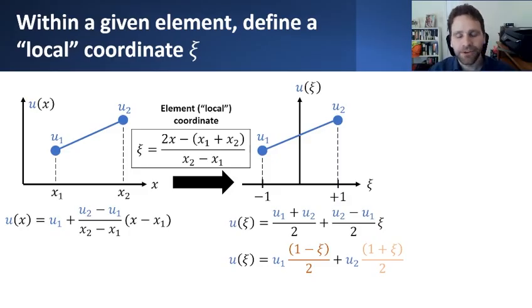All right, so within this element local coordinate system, I suppose that node 1 is located at the coordinate psi equals -1, and node 2 is located at the coordinate psi equals +1. So at those two locations, I have to recover the condition that at psi equals -1, I recover u1, and at psi equals +1, I recover u2. And otherwise, I need to come up with this representation of the function u, not as a function of x, but in terms of the local coordinate psi.